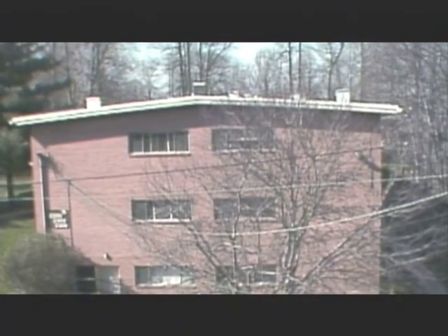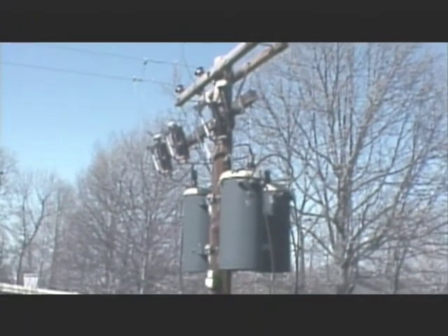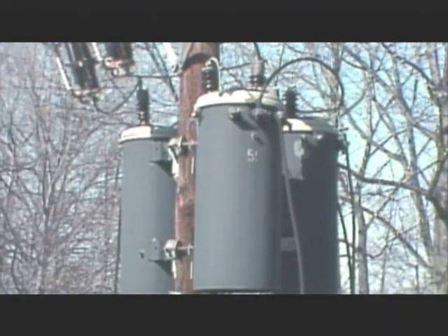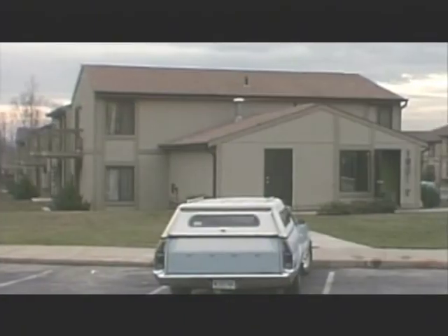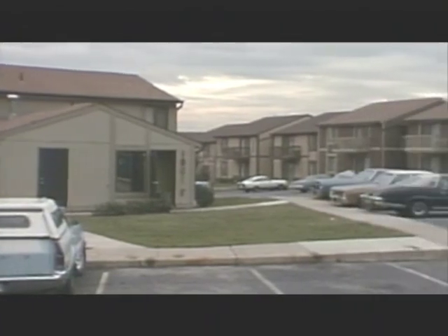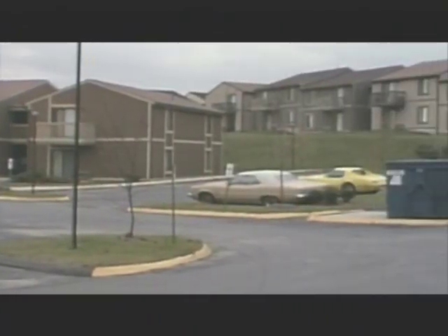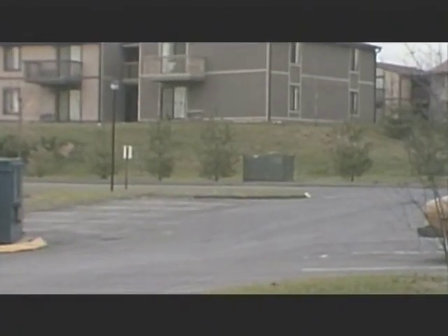In some cases, the load demand and equipment used by a consumer requires the use of a 3-phase transformer. In an overhead system, 3 single-phase transformers can be connected together to form a 3-phase transformer. Of course, not all transformers are located overhead on utility poles. In areas that have underground distribution systems, pad mounting is a common method of installing transformers.